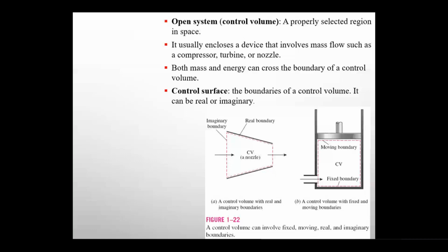Yes, absolutely. If I'll not have this, if I'll have it closed, I'll essentially have a closed system. All right? Clear enough? So let's say I have a geyser at home, and there's cold water which is at 25 degrees coming into that geyser, and I want hot water moving out of the system towards my bathroom. I want it to be at 32 degrees. Now I want to analyze how much heat should be provided to that geyser so that the cold water coming at 25 degrees centigrade should leave the system at 32 degrees centigrade.